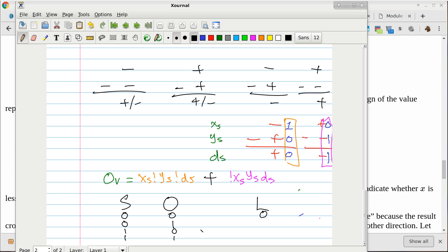The second row, the sign flag says, I'm telling you, the minuend is not less than the subtrahend. And then the lie detector goes beep, beep, beep. Then what do you say? Then you say, oh, the sign flag is lying. Whatever it's saying is the opposite of the truth. The sign flag says it's not less than, so the truth is it is less than. Okay. Put a 1 here.